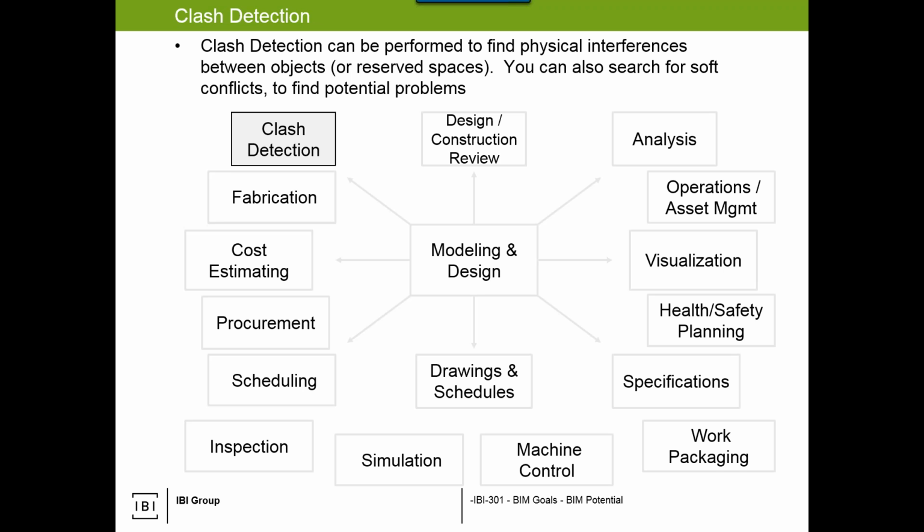They're designed that way. So there's that interaction that occurs with the automated routine, and then you have the ability to model reserved spaces. So some BIM authoring tools will say, put a reserved block in front of a door so that the handicap access to the door or the barrier-free access is accounted for, and anything impeding in that space will be marked as an interference. Very powerful. It allows you to identify those.